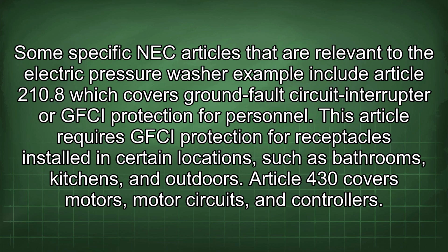Some specific NEC articles that are relevant to the electric pressure washer example include Article 210.8, which covers ground fault circuit interrupter, or GFCI, protection for personnel. This article requires GFCI protection for receptacles installed in certain locations such as bathrooms, kitchens, and outdoors.